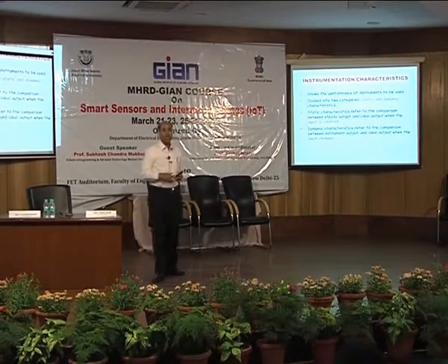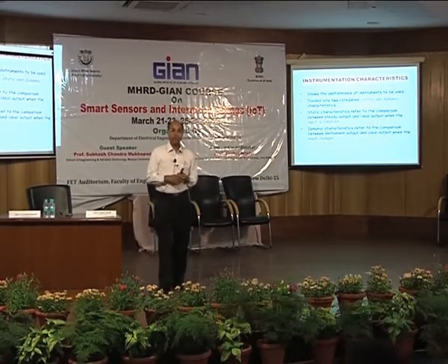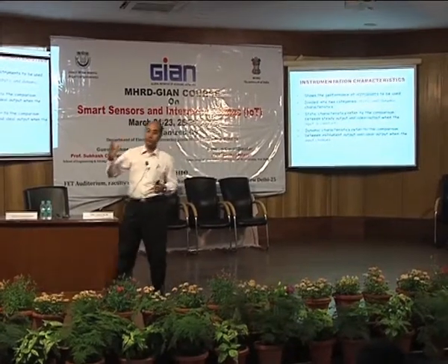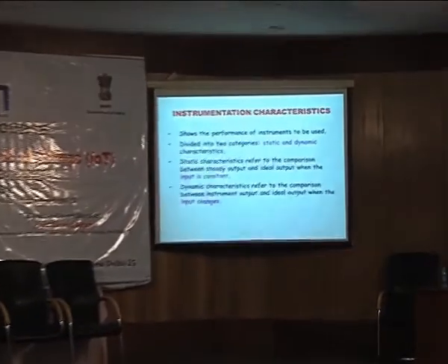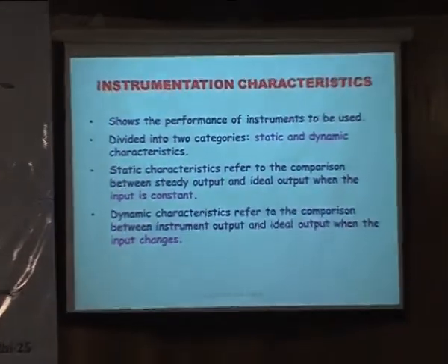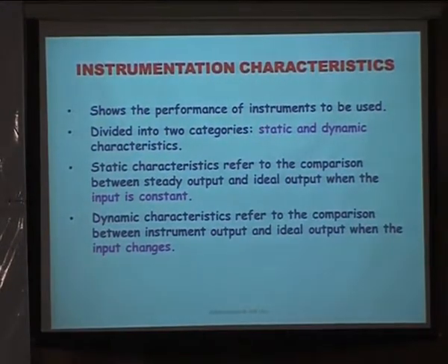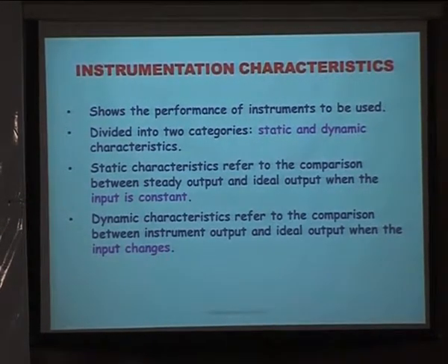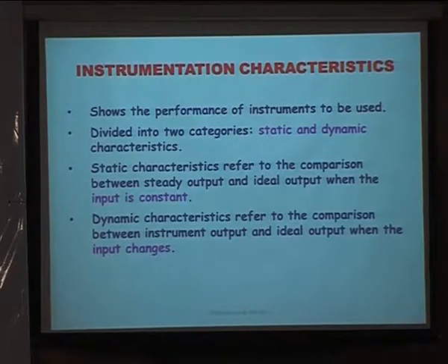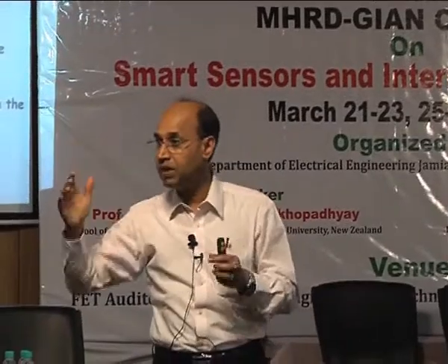Sometimes, in order to do that, for a test sample we give some input, keep the input constant, and we see the output. That tells us how much time the sensor takes. Even though you give a static input, the response of the sensor will not be instantaneous. It takes some time; the output may change slowly, and then it becomes steady.